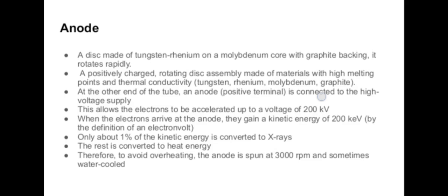Usually the modern rotating anodes are made from an alloy of solid molybdenum, titanium and zirconium, onto which a thin layer of tungsten rhenium focal track is coated. The specific heat capacity of molybdenum is higher than that of tungsten. The mass of the molybdenum anode is also lower due to its lower density. To increase the disc volume, the anode is backed with graphite. Though it increases the weight, it will double the heat storage capacity. Molybdenum and graphite have lower mass density and make the anode lighter and easier to rotate.